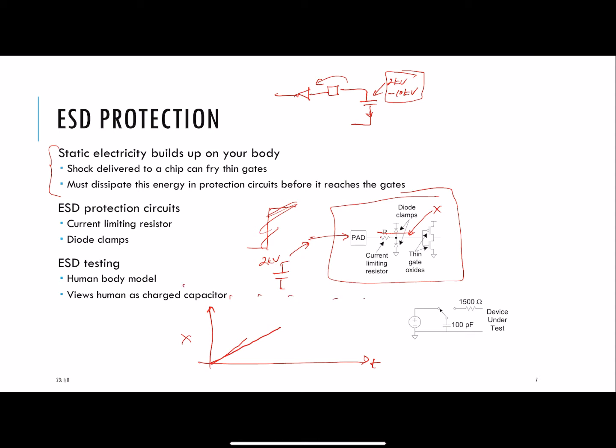Okay, let's say this is 2,000 volts. And let's say this is 1.2 volts. I'm drawing this in a break in the circuit. And then what happens is, let's say this clamp, this diode goes to your 1.2 volt supply. As soon as this node X goes to 1.2 volts plus a diode drop above it, this diode turns on and basically discharges this additional charge. So it kind of clamps that node to 1.2 volts plus a diode drop. That's when it latches, that's when it fires off. So that's the basic idea behind it.